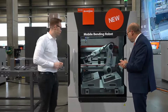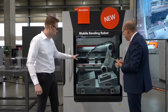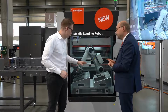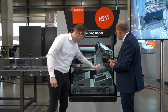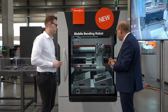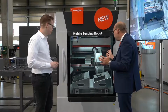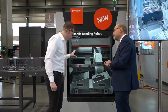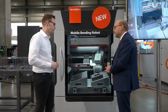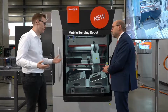And I also heard that there is another kind of pallet, a bigger one. Yes, so right now you see 2 pallets in front. It's also an option and a feature that we have, that we have 1 pallet, so you can handle bigger parts. Okay, bigger parts than this one, which looks like 300 times 400? Yes, 300 times 600. So the biggest part right now you can handle at 1 pallet is 600 by 300 millimeters, and with 1 pallet you can handle also bigger parts. Okay.